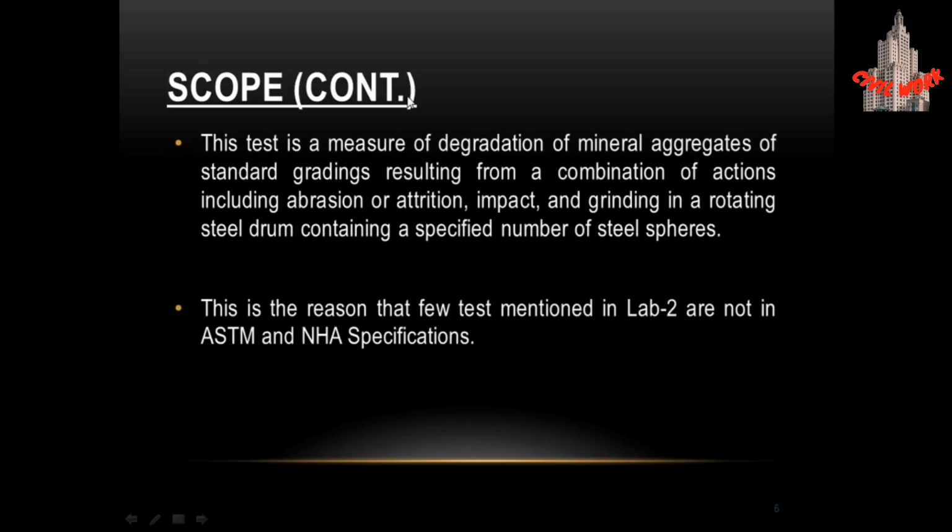This test is a measure of degradation of mineral aggregates of standard grading resulting from a combination of actions including abrasion or attrition, impact and grinding in a rotating steel drum containing a specified number of steel spheres.